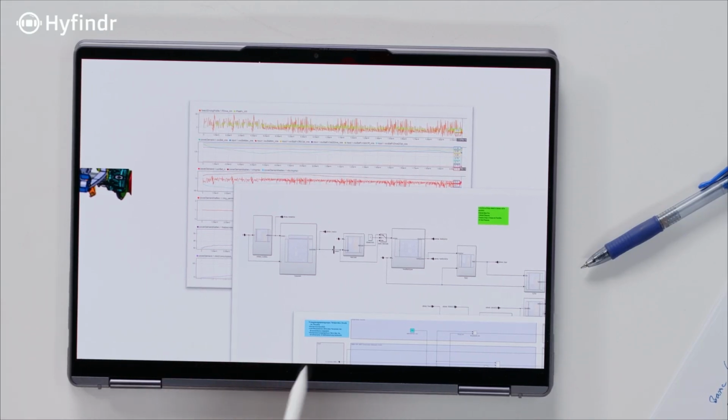At first, this is a basic model. There are all components in the balance of plant that are necessary to run the fuel cell stack, but these are generic components. With the load profile as input to the simulation model, we get a kind of requirement sheet: what compressor do we need, what is the mass flow, and so on. So several parameters for designing the fuel cell system.